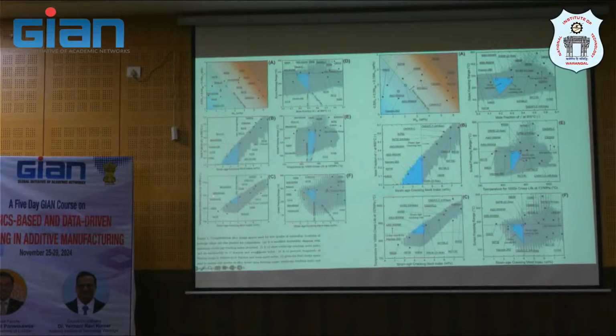And then we can generate the different rankings, because the screening is based on the metallurgy that we identify for the window. Let's say a higher mass fraction of gamma prime at 900, strain age cracking, because we're talking about cracking at that time, and creep life at 1000 degrees centigrade at 137 megapascal.